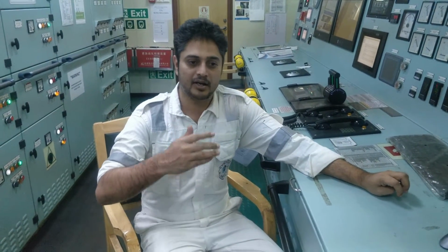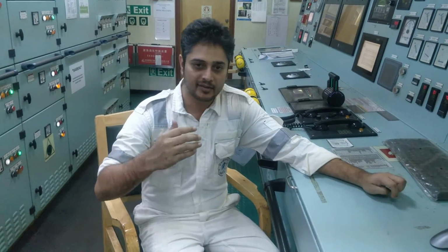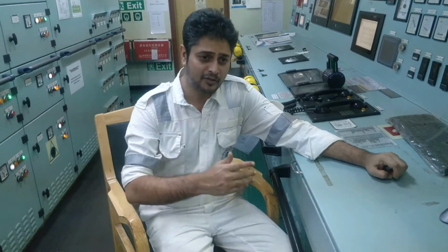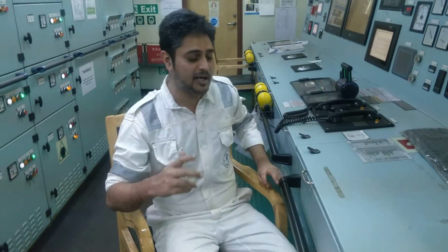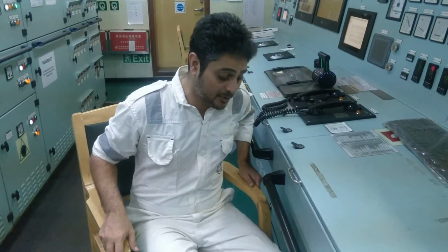Now assuming that the ECU has received the signal from the EICU telling that the set point has been increased from half ahead to full ahead, from the ECU the signal goes to the CCU, the cylinder control unit, through the MPC, that the set point has been increased, so you do accordingly. Now what the CCU does, that is what I want to explain in this video in a precise way.